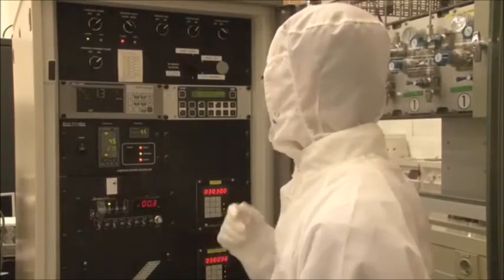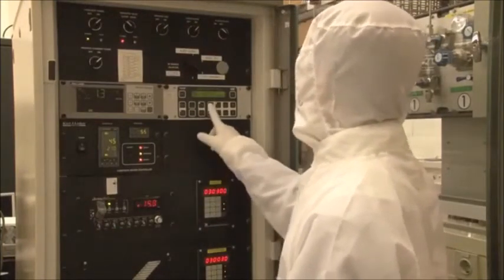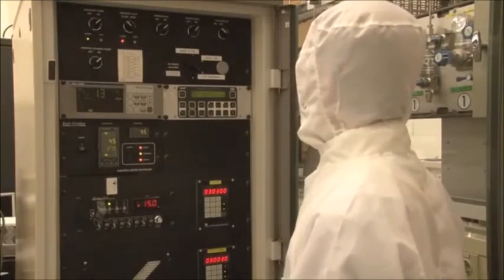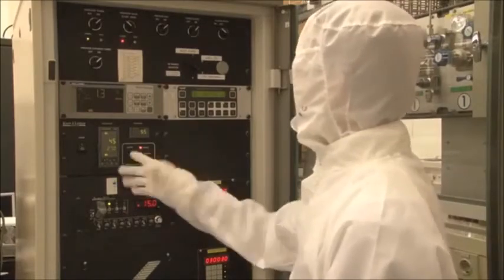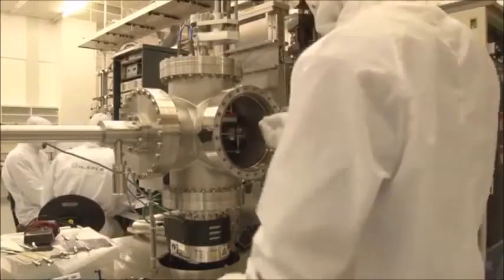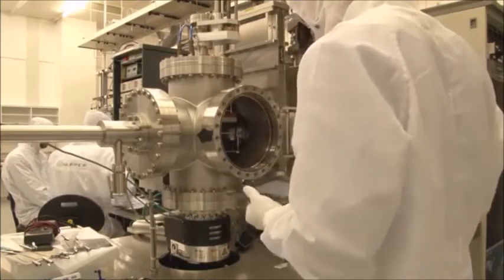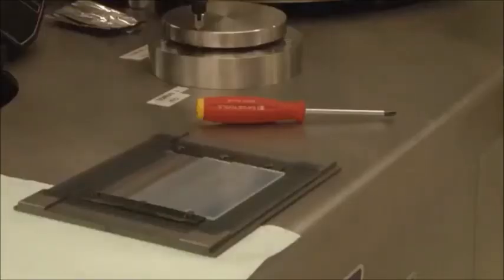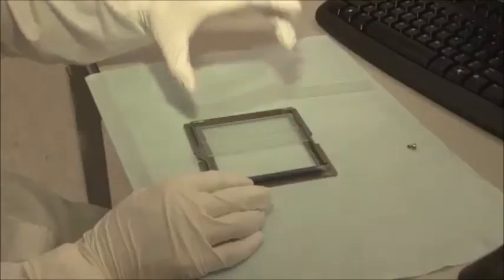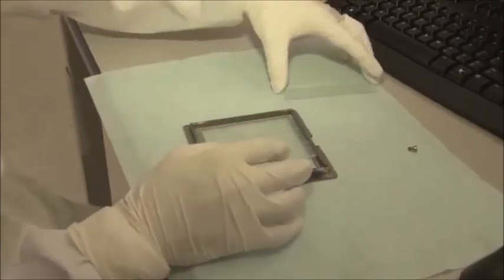During sputtering, the zinc oxide target is bombarded using an ionized noble gas like argon. The generated aluminum zinc oxide species are sputtered into the chamber and deposited onto the substrate. Here you see the sputtering plasma. After the sputtering processing step, we have a glass plate with a tin oxide with on top a very thin zinc oxide layer. Next, the samples are mounted into a different substrate holder.